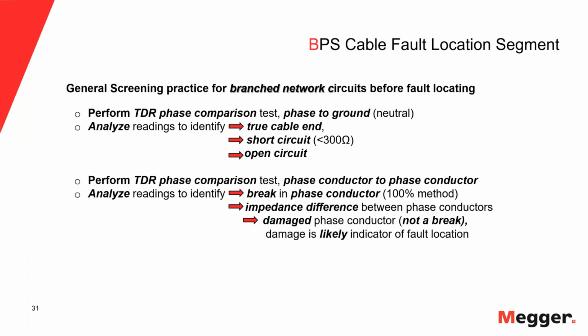But we can give it a shot, because if we see something, it's a very valuable result. We can also do face-to-face comparison, like I was explaining on the industrial circuits, but overall you have to keep your expectation low on using a TDR in these branch network systems. So it pretty much defaults back to the insulation resistance test.